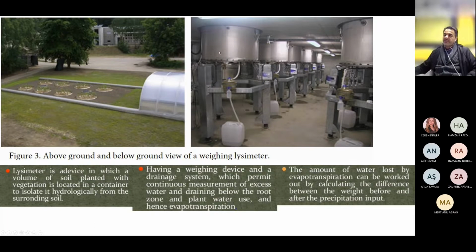And after a day, when you measure the difference between the weights, and when you know how much water goes up, therefore you can use the water balance equation that we already talked about to find the loss. And here the loss is nothing other than evapotranspiration, because we have some soil, we have vegetation, and therefore we measured some values that we can use in the water balance equation to check the amount of evapotranspiration.